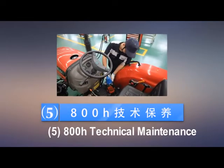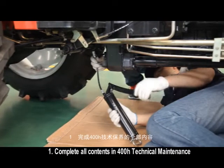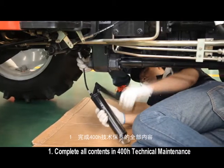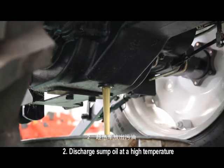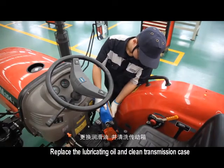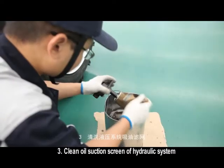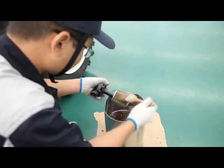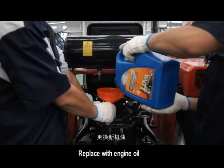5. 800-hour technical maintenance. 1. Complete all contents in 400-hour technical maintenance. 2. Discharge some oil at a high temperature. Replace the lubricating oil and clean the transmission case. 3. Clean the oil suction screen of the hydraulic system. Clean the inner chamber of the lifter casing. Replace with engine oil.